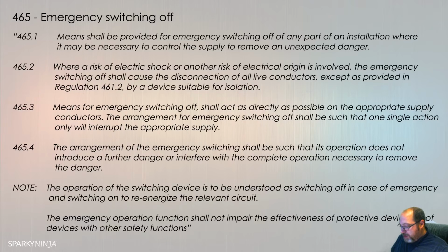Okay, so I can only use a semiconductor as a functional switch. It's a functional means of operation. Similarly, a plug and unswitched socket outlet, right at the bottom of the page there, I can use as an isolation means, and I can use for functional switching. I can't use it as an emergency switch.